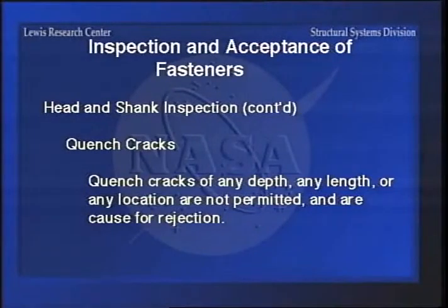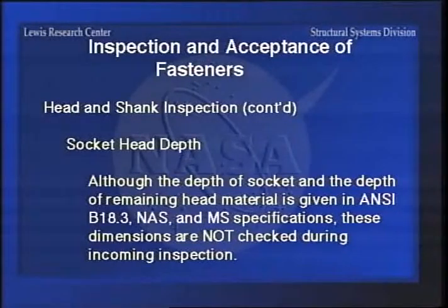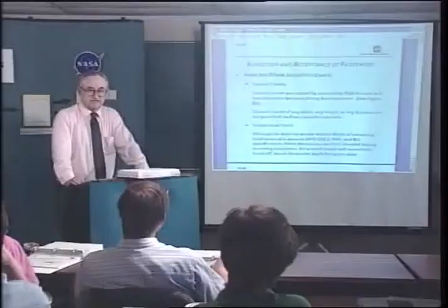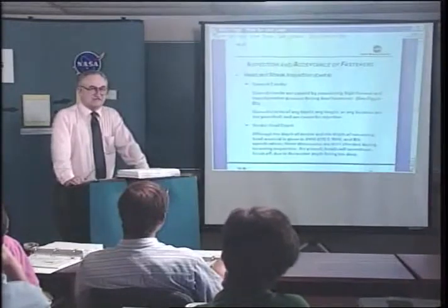And here's another one. This is a pet peeve of mine. Socket head depth. Even though if you go to any of the ANSI specs or mil specs, any of these on socket head fasteners, they give dimensions for the depth of socket, I have yet to find anybody that's ever checked one.